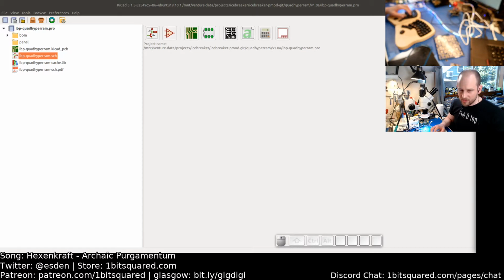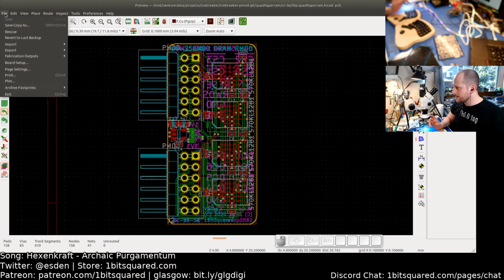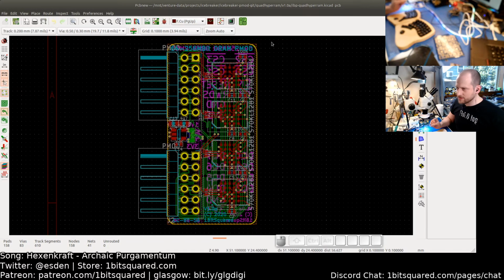We will be using pcbnew, that's how the binary is called for PCB layout. eeschema would be for schematics. And pcbnew is what we need, and we need to start it standalone. Standalone, it gets a few additional special menu entries that we don't get in the full start version. So here you will see there is no append board in this menu, which we will need to be able to make our boards.